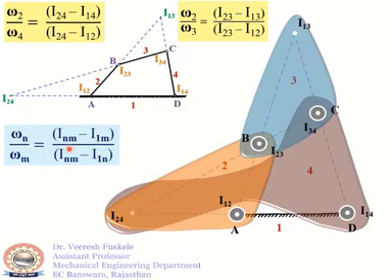So we can see from this generalized formula, if suppose n is 2 and m is 4, then we will have 2 here and 2 here, and m is 4, so we will have 4 here, 4 here, then we have 1 and 1 here, then we see that m goes here and n comes here, that is 2 goes here and 4 is here. So this is how we can write this angular velocity ratio for any link as per the given problem.